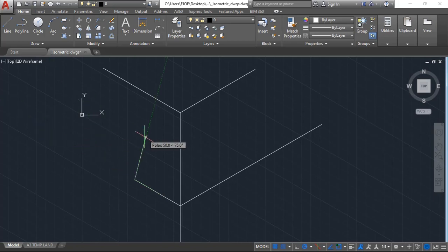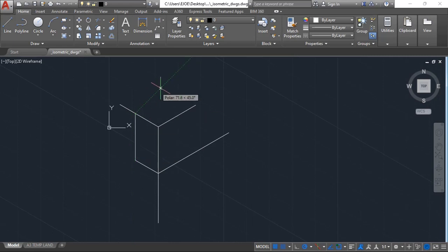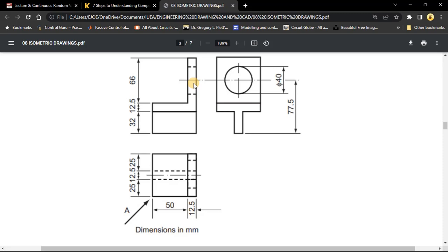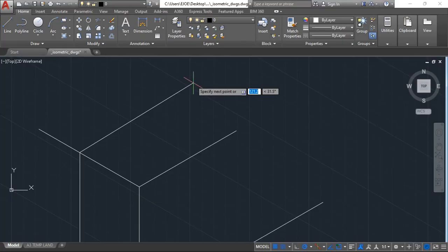So those are 3 points that I've created. Now I'll go vertically upwards and get that end point. So I'll still continue in this direction, 30 degrees, I forgot that, take that distance. It should be 50 plus 12.5. So let me make that distance right away.